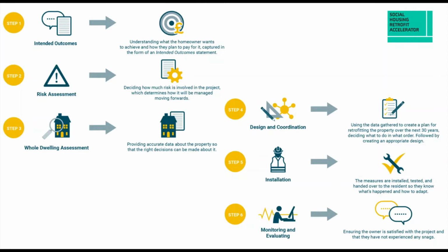You're going to want to actually assess, did we achieve the outcome of giving them a more comfortable house? Because if we go back after the fact and we find out it's full of mold, it's still drafty, it's still cold, we've gone through this whole process, we have not achieved the intended outcomes, the retrofit hasn't worked, and then we need to go back and we need to rectify it. So that is the PAS 2035 process.